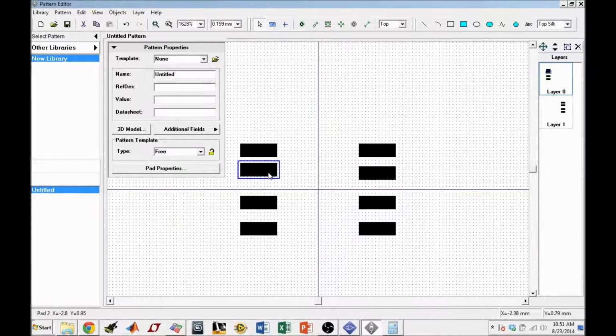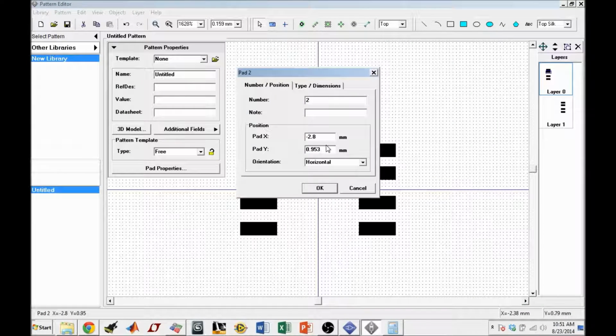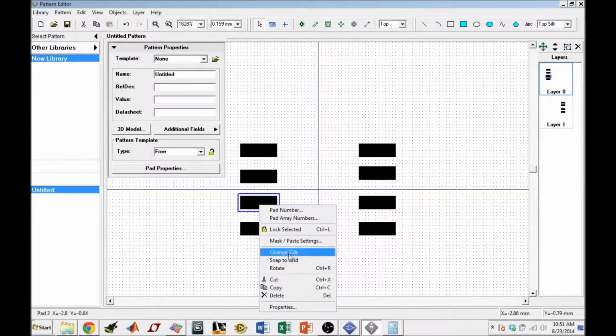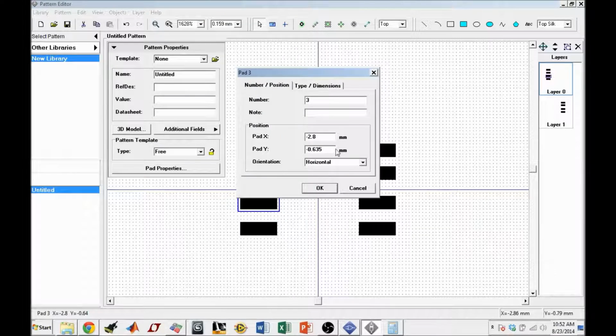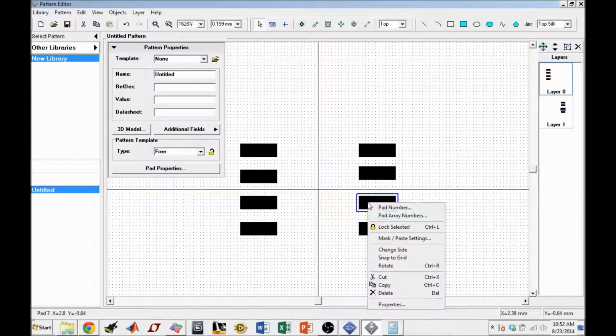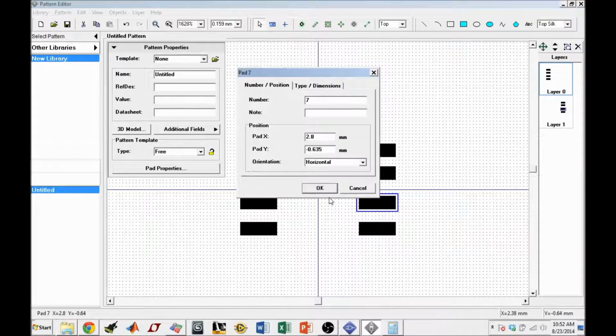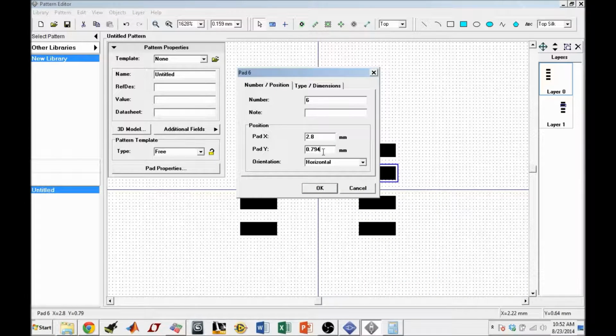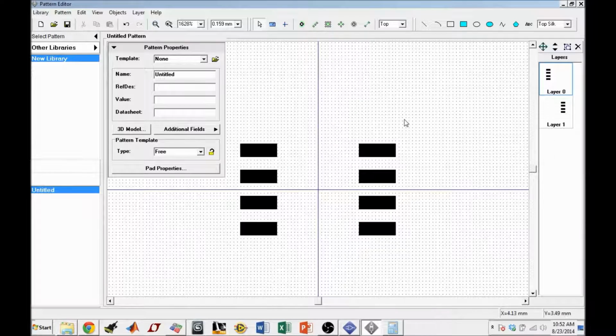So right over here, go ahead and change the property. So this is 0.635. Enter. Then therefore this one should be negative 0.635. And actually, I mapped it perfectly even without doing anything. Check the properties here. Nah, that's good as well. And let's check over here, properties. So this one should be 0.635, my bad. All right, so we actually now have the correct pad layout.